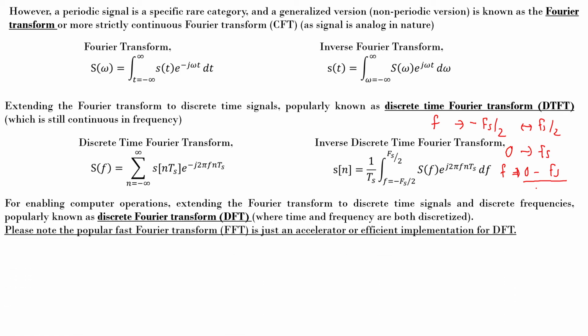The fundamental condition in discrete Fourier transform is that when you take discrete Fourier transform of a sequence, the assumption is that the sequence is actually repeating outside its considered region. So let's say you consider a small n samples in the signal. Then the discrete Fourier transform assumes that the signal is replicated.